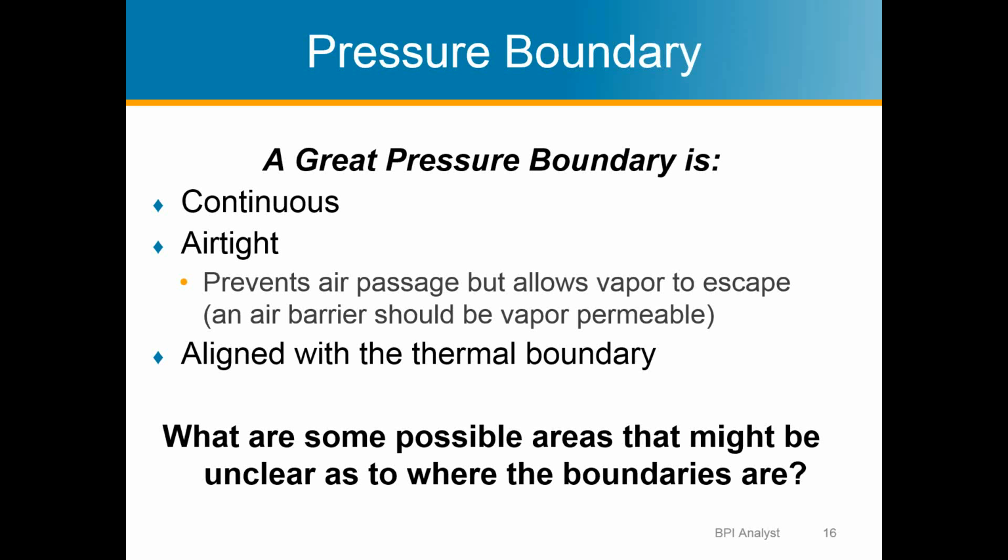So, possible areas where it's unclear where the boundaries are. In most construction, just the way the construction industry is, typically behind a bathtub, if it's on an exterior wall, there's an issue with the alignment of the pressure boundary and the thermal boundary.